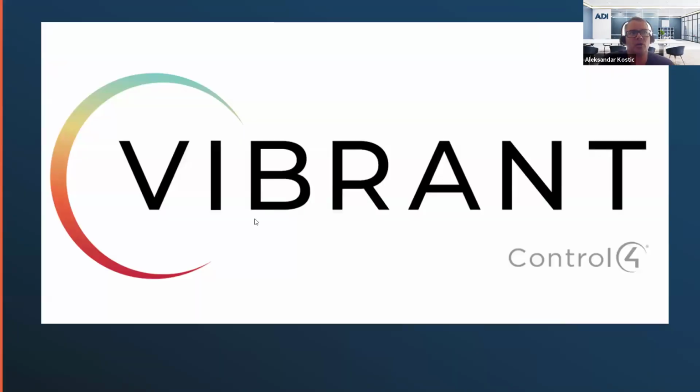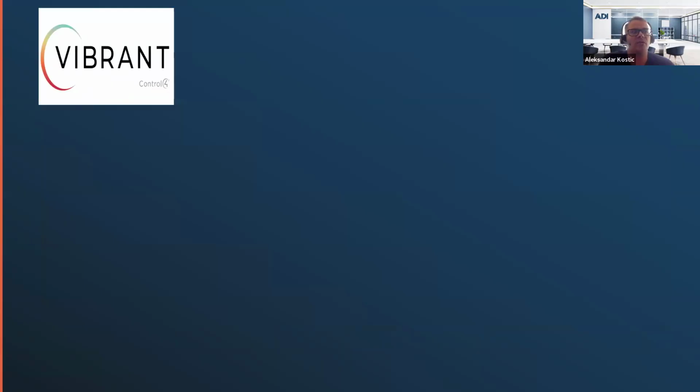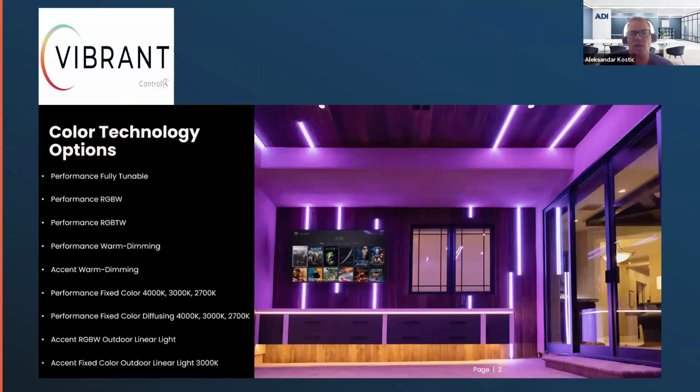And when we speak about Vibrant, we speak about different types of LED tapes. We have from the simplest fixed color LED tapes through the fully tunable white, where you can change the temperature of the white and the brightness. Also, we have warm dimming LED tapes, which are also quite simple with a single channel control, but the temperature of the white and the brightness cannot be controlled independently. Each level of brightness corresponds to a specific temperature of the white.